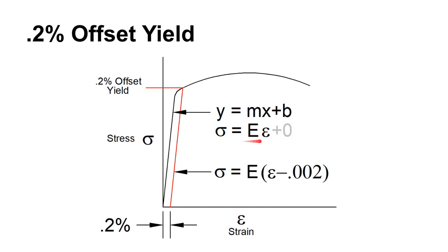So this is a good way of understanding this nice linear portion of the graph, this elastic region. It could be defined with this equation. Okay, so if we already knew Young's modulus, all we would need to plot an equivalent sort of model of this material in, say, Excel is to just plug in this equation. Okay, and that would model this part of that graph for us.